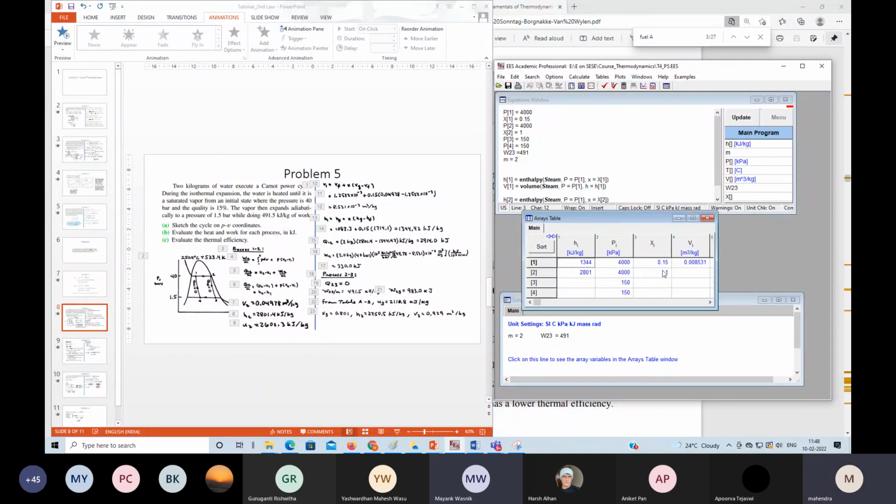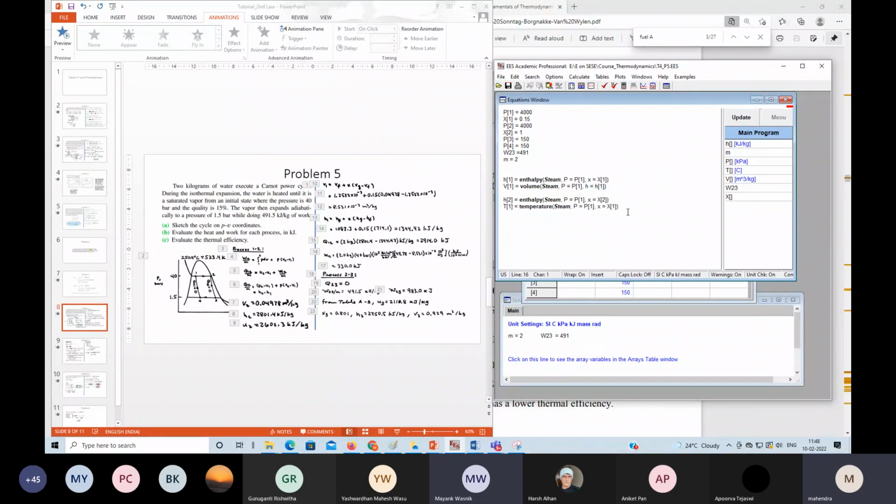So what we have entered over here, temperature, right? Yeah, it is temperature. Any question? Somebody's mic is on. Okay, this is 250.4 degrees centigrade. So you can go and check with your tables at this particular pressure, what is the saturation temperature. That we can get over here.